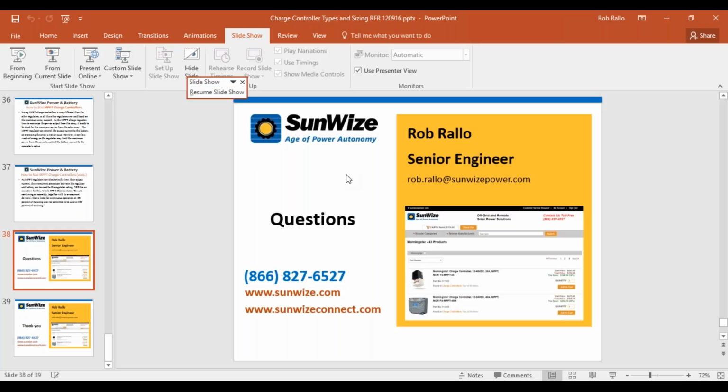They're required by NEC, and that's a whole other topic of discussion of when you need it. So if you have multiple modules or strings in parallel, you most likely will require those for various reasons. If it is a single module or a single string, you may not. Generally, you do not need it there as long as you have a fuse or circuit breaker at the battery.